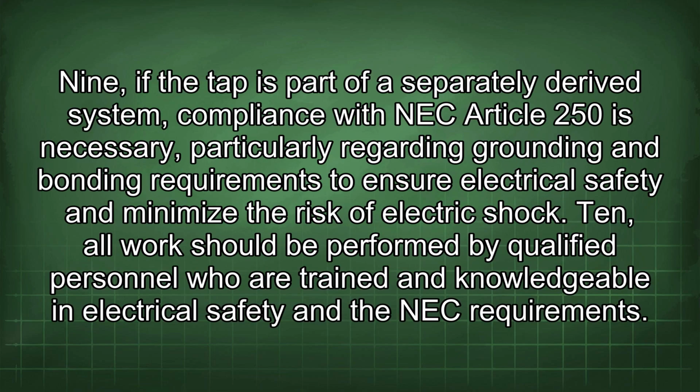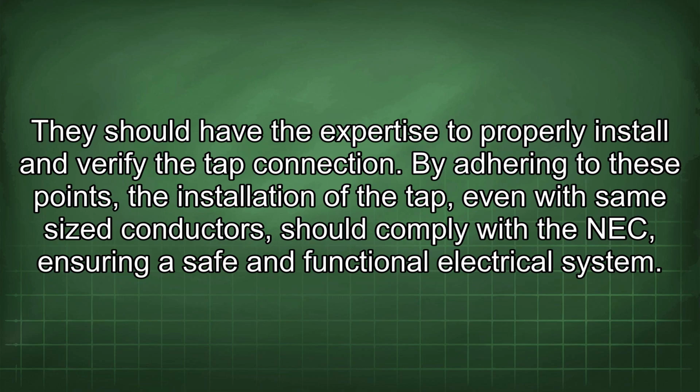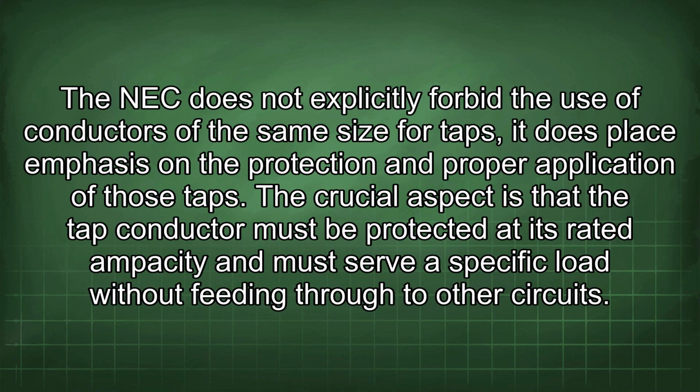9. If the tap is part of a separately derived system, compliance with NEC Article 250 is necessary, particularly regarding grounding and bonding requirements to ensure electrical safety and minimize the risk of electric shock. 10. All work should be performed by qualified personnel who are trained and knowledgeable in electrical safety and the NEC requirements. They should have the expertise to properly install and verify the tap connection. By adhering to these points, the installation of the tap, even with same-sized conductors, should comply with the NEC, ensuring a safe and functional electrical system. The NEC does not explicitly forbid the use of conductors of the same size for taps.